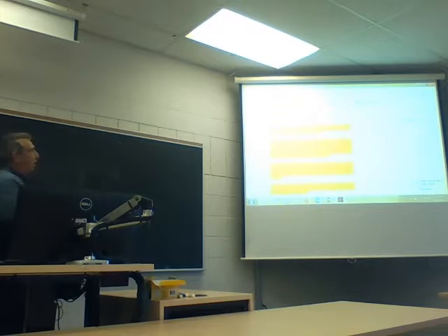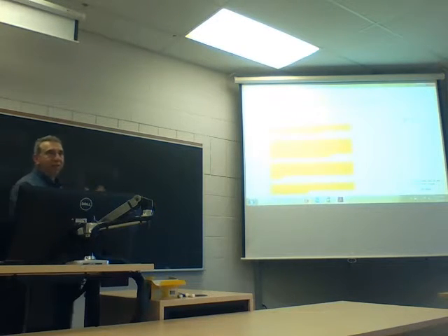Air is drawn in at the center of the eye, the same as a centrifugal pump. So at the center it draws it in. The rotating centrifugal force of the backward vanes throws the air out, like he was talking about. So it actually throws the air out. The impeller takes the high velocity energy and converts it into pressure.